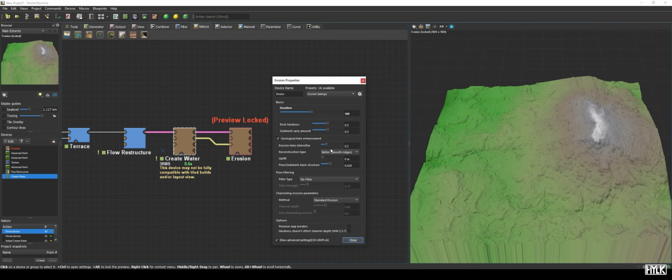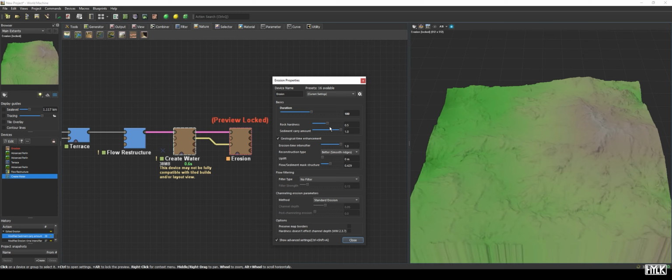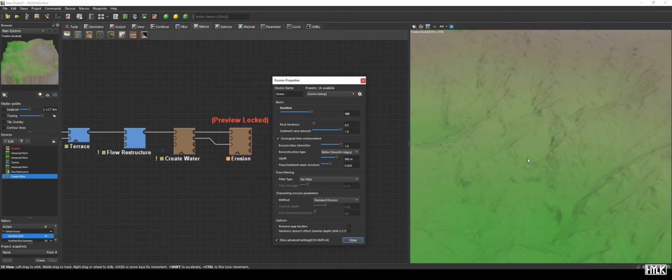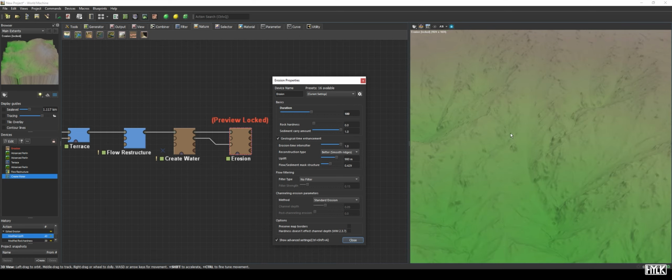The Erosion-time intensifier is not really aware of the water system and will erode the terrain around the river and water away, especially for higher values, creating for some very unnatural looking situations, as you can see. The uplift parameter is a clever way to lift the surrounding terrain, ensuring the rivers and lakes are bedded into the terrain again.